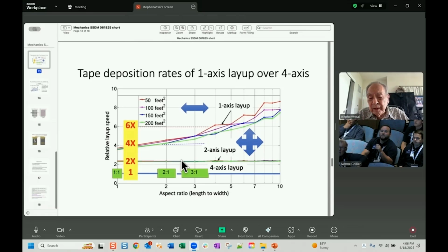I'm not familiar with the different ways of dropping plies, but in the case of double, the key is homogenization. Homogenization across the thickness, also across the plane of the structure. So our recommendation is to homogenize the entire structure or large areas, and then your ply drop becomes very simple, because you don't have a stacking sequence or blending issue as you do with quad.